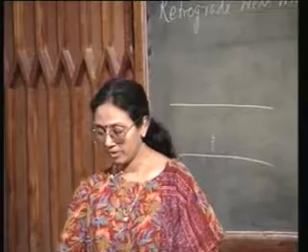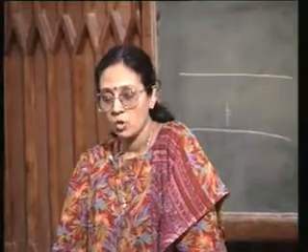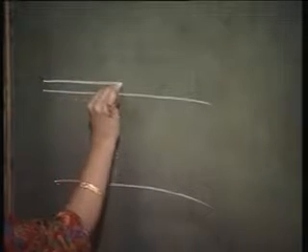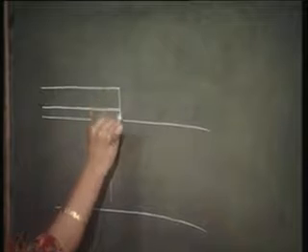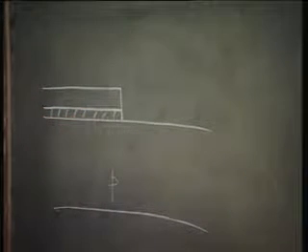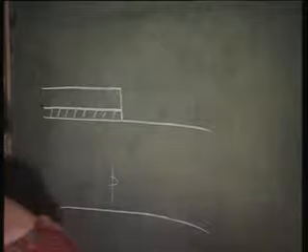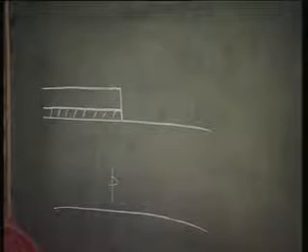Okay. Now, in the first step I am going to have an N well technology. So, in the first step I must demarcate the regions for the N well. And remember, this is going to be a retrograde well. So, first of all I must have an ion implantation to have this heavily doped region lying underneath the N well. So, to this end I first protect certain regions with an oxide nitride cap, and I do a blanket implant.